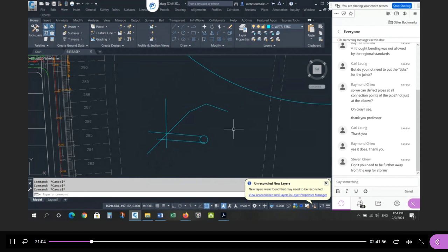Now 3 meters is a number that works for nominal depth. If you have unusually deep pipes, like if this is way down here, then you need to move this a lot further away so that the toe of the slope that holds up the pavement is far enough away. That's really what I'm basing it on. But on a typical depth sewer, 3 meters from the edge of pavement across should do. So it's a rule of thumb, but you have to look at the nominal depth.